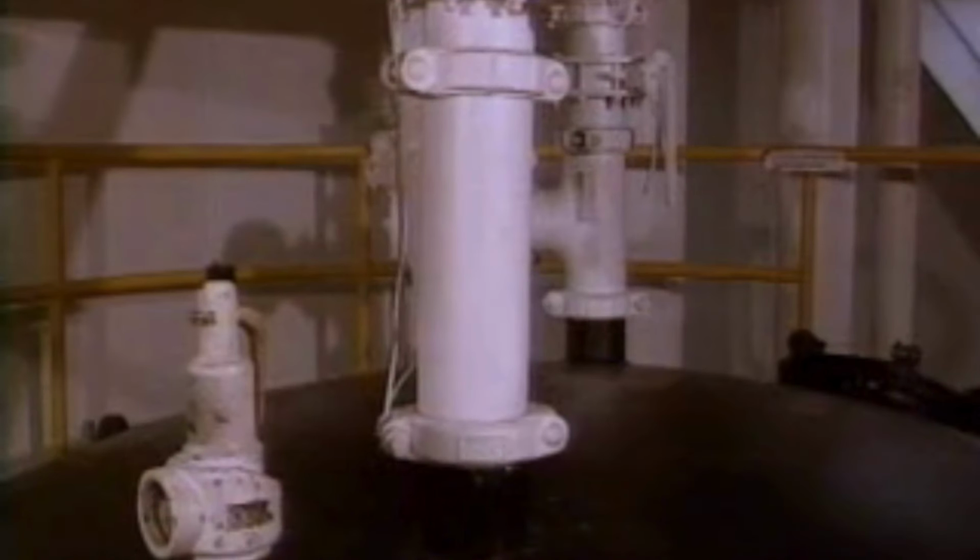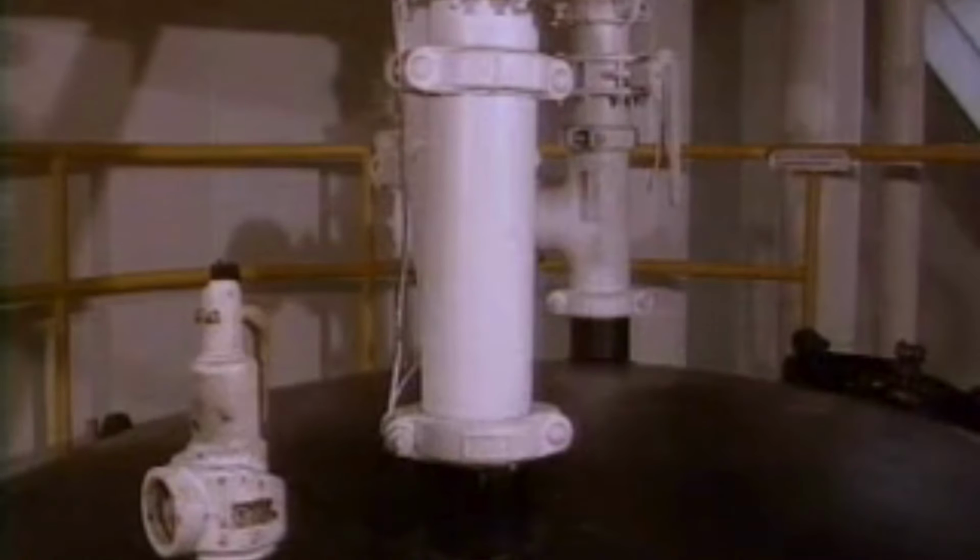The discharge line is used to move bulk from the P-tanks to the surge tanks or to other P-tanks. You might notice that the fill lines operate from the top of the P-tanks and the discharge lines operate from the bottom. There's always a union where the two lines are joined together. This allows the material that's routed into the discharge line system to be routed to the fill line system, which in turn delivers the materials to the various tanks.